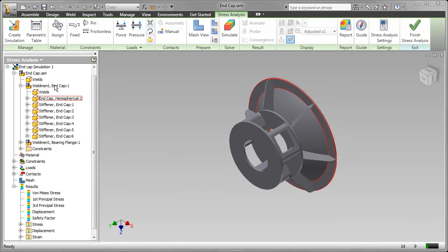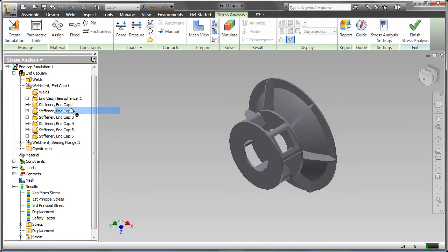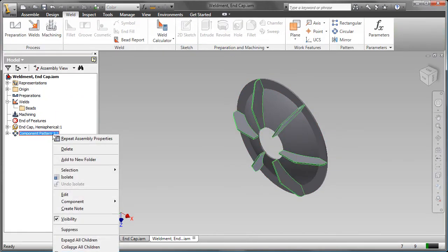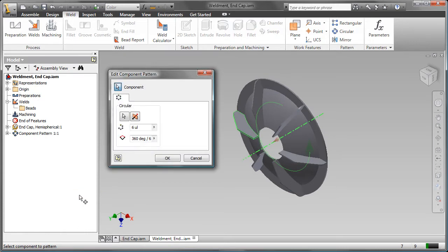The final optimization of the design is varying the number of ribs. The ribs help to reduce the unsupported length of the hemisphere so it can be thin-walled without having too much displacement. Because the hemisphere is stronger at the ribs, it keeps the total displacement in check. But how do we know if 6 ribs are enough or can use fewer than 6?